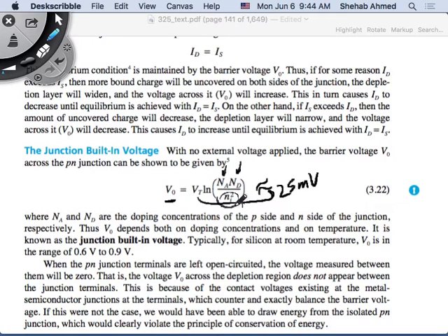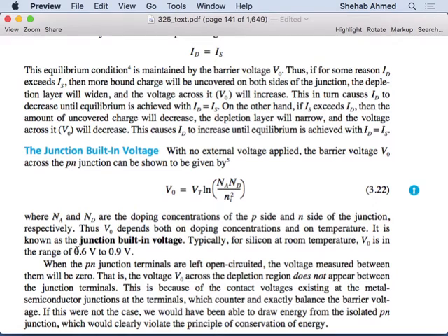So these are all given. I'm just telling you that this is what this barrier voltage equals from the physics. We did not derive it, and we will not derive it here. I'm just saying, this barrier voltage. We said that this barrier voltage develops due to the diffusion happening, and then it also helps the drift happening. So the steady-state barrier voltage is due to having acceptors, having donors, as well as some intrinsic properties of silicon, meaning the minority carrier is moving as well, right? So that's what this means here, and this will become a very important range of numbers.